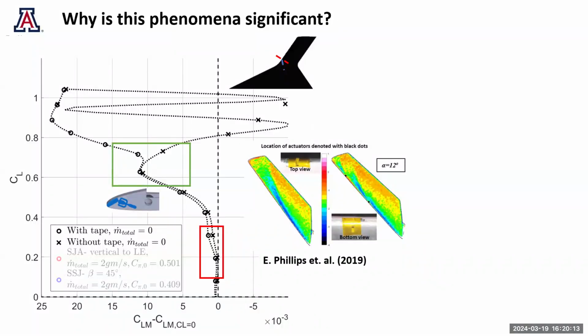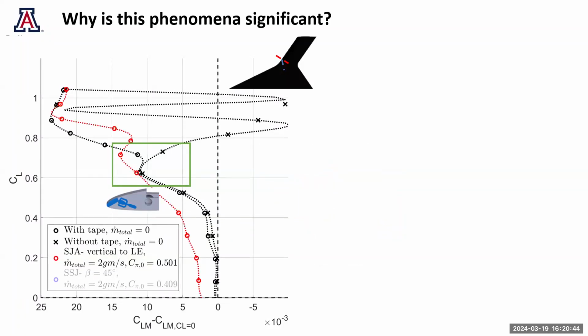When we have slots on the wing, we see that this large vortex development is broken down into different leading edge vortices. So, taking inspiration from this work, if we introduce a slot here, we effectively affect how the leading edge vortex develops on the outer part of the wing, and hence we get either a nose up or a nose down pitch moment.